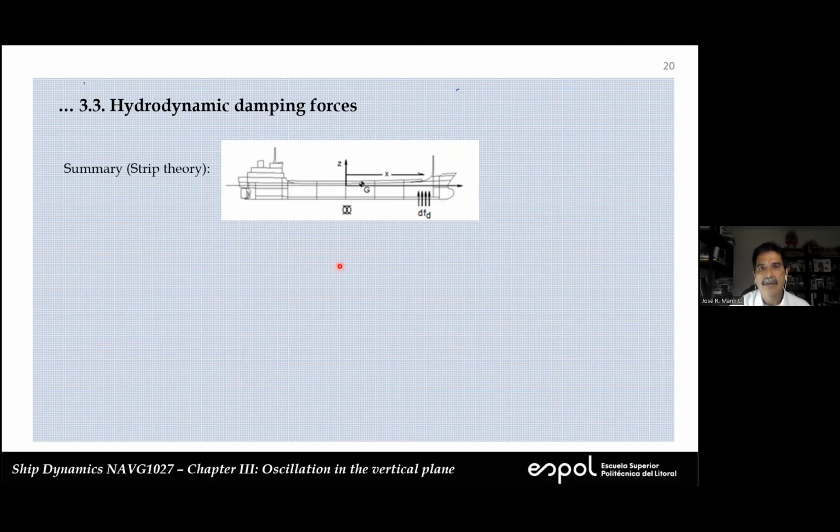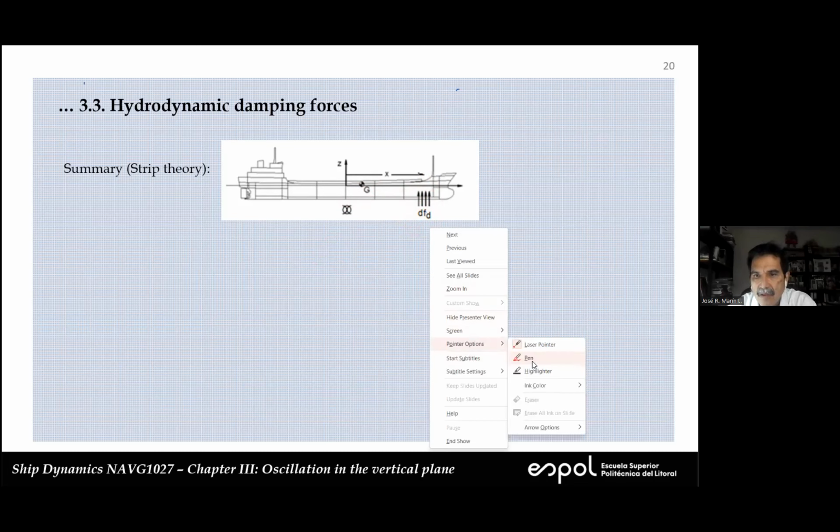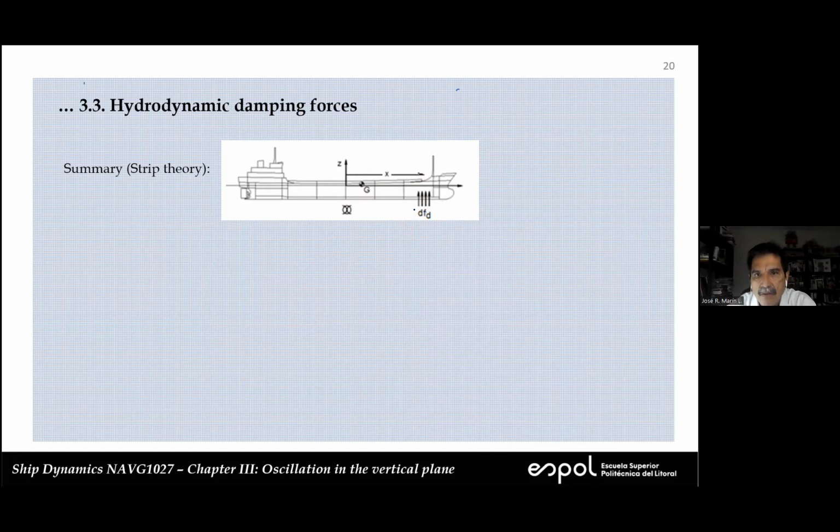Let's consider that for each one of these strips, we can solve and calculate the force. Remember, this is incorrect. This is not differential. So this is multiplied by dx, and this is dF. So this is the differential of the force, and that's equal to force per unit length times length. So please correct in your class notes.